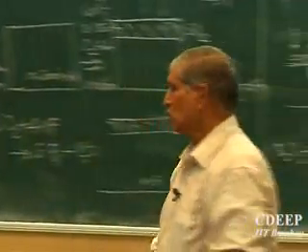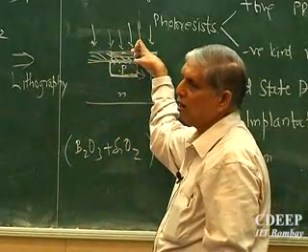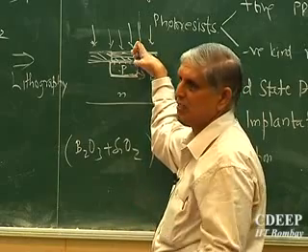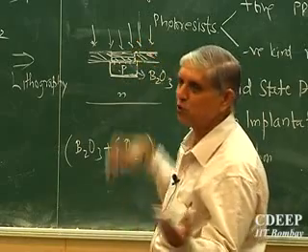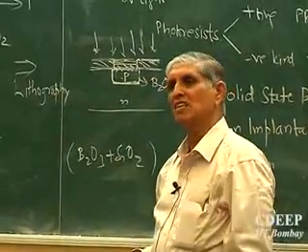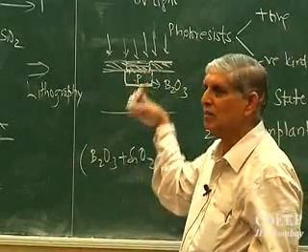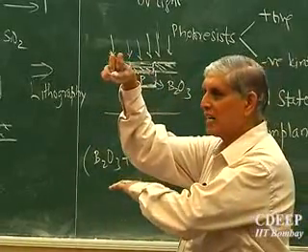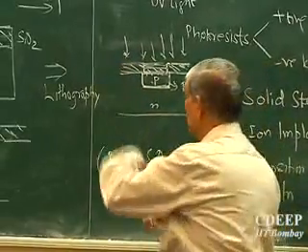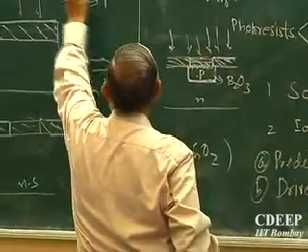Is that clear? So this ion implantation can be done for phosphorus, or for boron, or for arsenic, or for antimony, or indium, any source I have which I can ionize, those ions I can pull by electric field. And how do I focus the beam? By XY deflector plates, both electromagnets. Okay, I can focus the beam. I may have a smaller beam hitting here, then hitting here.